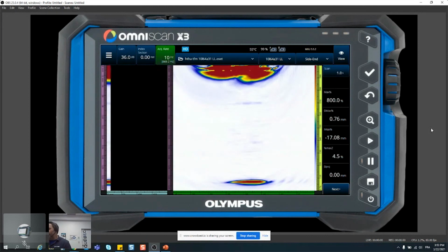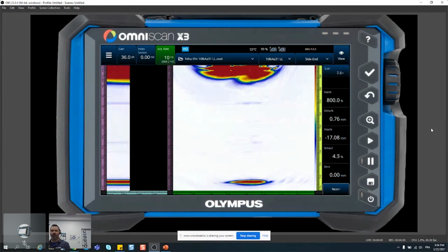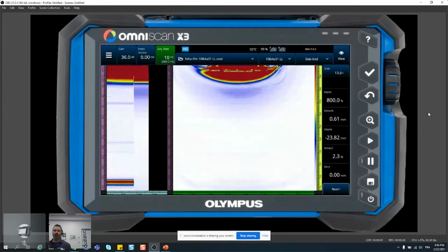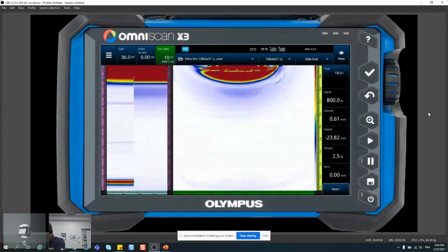Of course, that helps transmitting all this near field inside the part as I mentioned. But since probes are quite expensive, and you're very likely to use it with a shoe attached or a wedge, I figured that it might be good to actually demonstrate this with a 0-degree wedge rather than without.